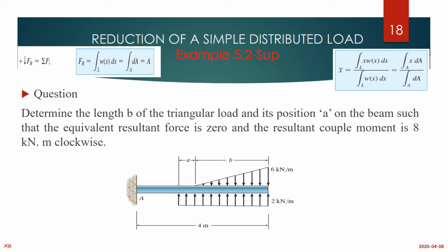joint, which simply means you are supposed to have another member facing this direction in the X and the other one in the Y. If the moment is going like that, you can assume you're forcing the X to be facing the left side and the forcing the Y to be facing up. When you get the negative, then it shows that your assumptions were wrong. If you find positive, then your assumptions are correct.